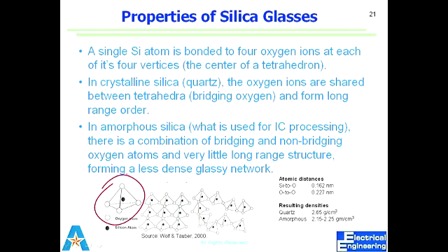How dense are the tetrahedrons? How many oxygens are bridging with respect to non-bridging oxygen? So it's a very important criterion because we see glass everywhere. We see silica, we hear silicon dioxide, we see quartz, we see all sorts of different materials which are essentially silicon dioxide, which are essentially glass, but they have very different properties based on this.